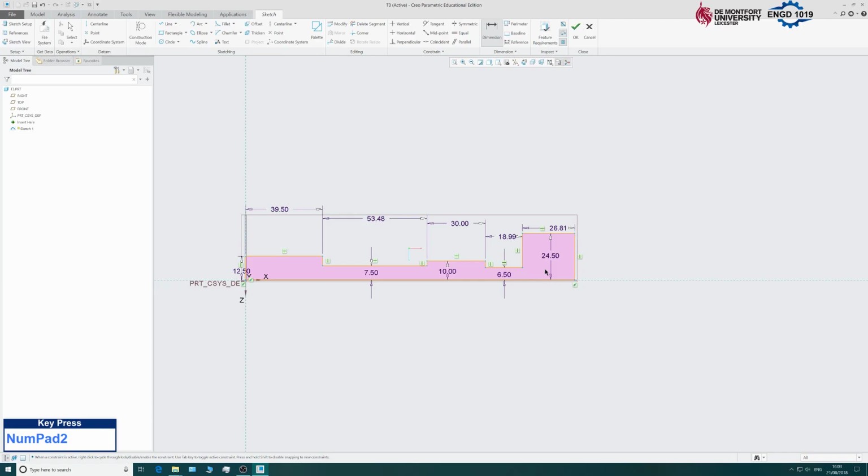So it's quite common on engineering drawings not to actually display the threads, because they can be quite complicated to model and they don't necessarily add that much to the engineering drawing. So as long as the manufacturer knows what you want, then you don't necessarily need to show it. So that's what's been done here. It's just a symbolic thread, and it's saying that it should be an M16. So that means that the actual diameter of this is 16 millimeters. So we'll use 8.